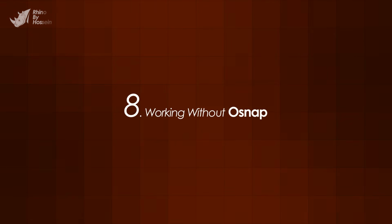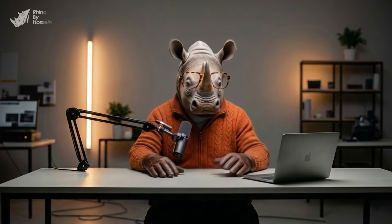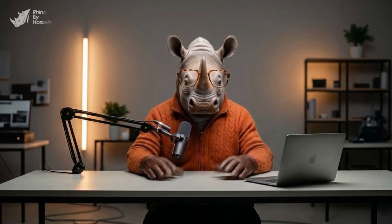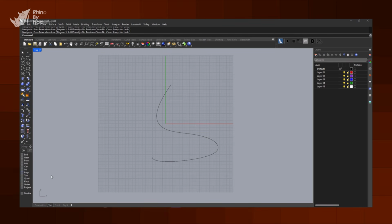8. Working without Osnap. One of the most dangerous but at the same time deceptively simple mistakes in Rhino is modeling without Osnap enabled. At first, it might feel like turning it off gives you more speed and freedom. You're no longer forced to snap to exact points, and it seems easier to draw lines and shapes quickly. But the problem is that nothing is actually precise anymore.